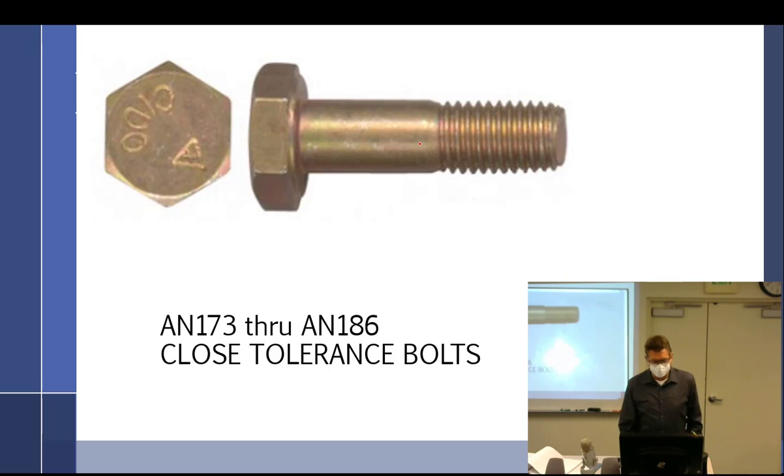Okay. But you wouldn't need a washer right after the head either? I do. Depending on the application, I'll use 2 washers. I'll put 1 washer underneath the head. Always 1 washer here. Always, always, always. And then maybe the lock washer comes next. So it's washer, lock washer, then the nut.